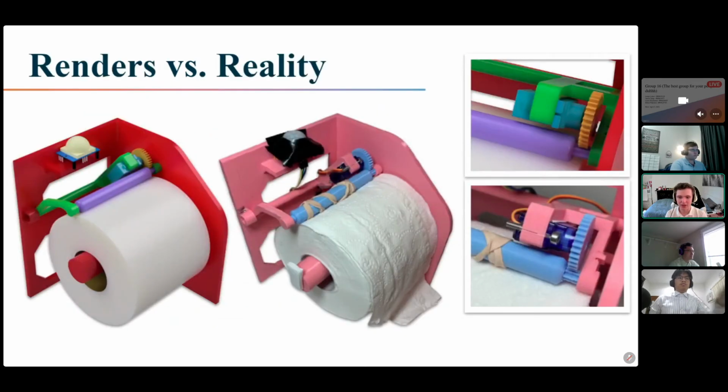So here's our mechanical design. It came together mostly as expected. The 4:1 gearing ratio dispenses 2 sheets per second, which is very quick and definitely above what we expected. We were going to hold pressure on the roll with an elastic, but the servo didn't have enough torque to overcome the inertia to get the roller spinning, so we just let gravity do the work, and that's what pushes it down.